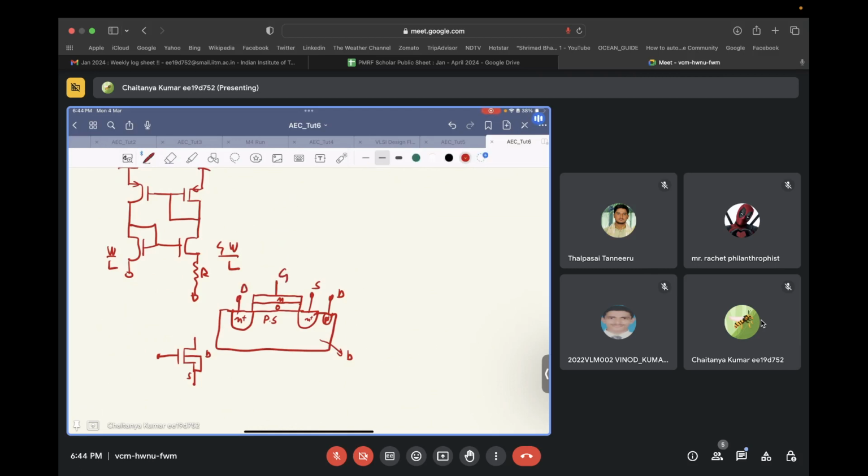Okay. So what happens is, generally, for theoretical purposes, while understanding initially in analog electronics, we assume that body and source are shorted. But when you actually design the transistors, this body is basically just the p substrate, and this is common for all the transistors that are in your close vicinity. So you can't actually short your body and source.